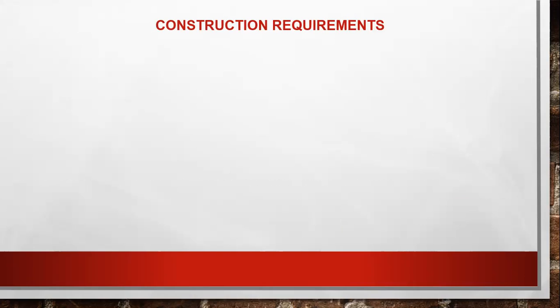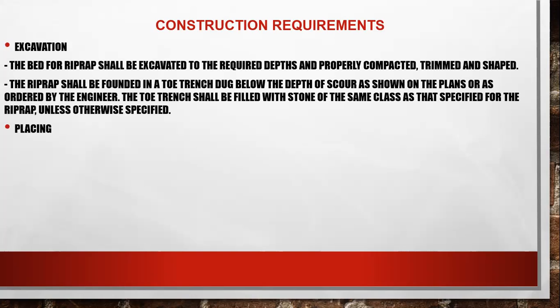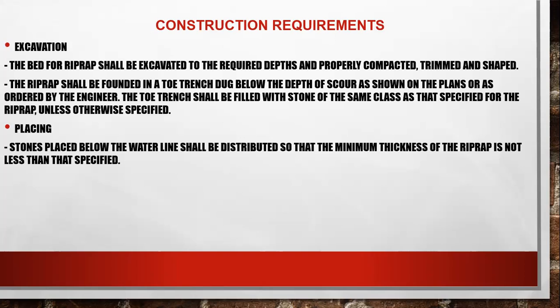These are the construction requirements. First, excavation. We should excavate to build a foundation or the bed of the riprap. Next is the placing. We place the stones accordingly. If the stones are not piled properly, it can cause collapse of the structure.